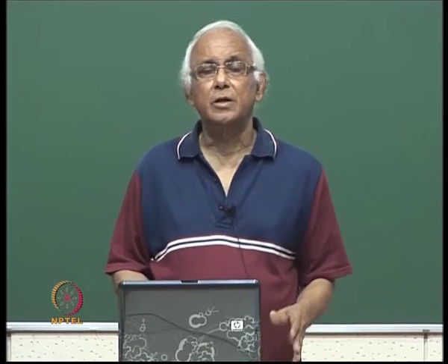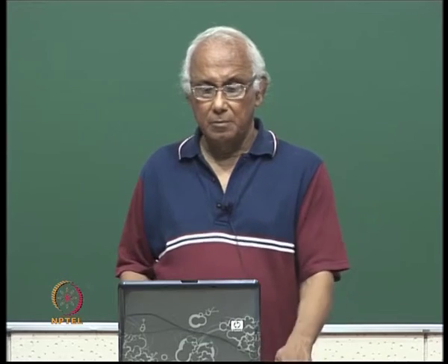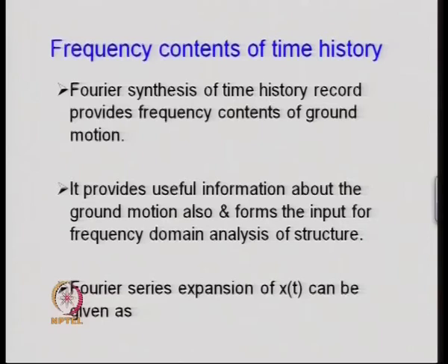The frequency contents of the time history are obtained by the classical Fourier synthesis of the time history record. It provides useful information about the ground motion, and also forms the input for frequency domain analysis of structures.